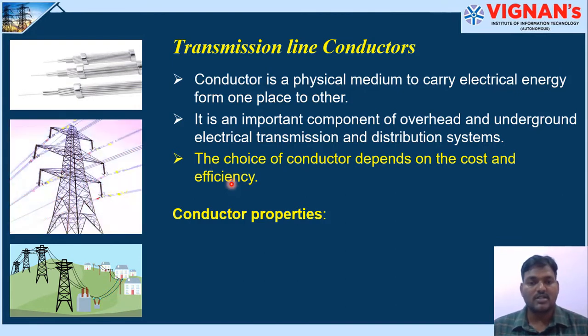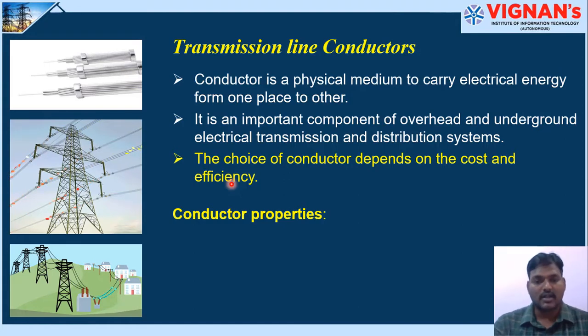Similarly, the resistance depends upon the length and area, or you can say it depends upon the volume of the material. So if you choose properly the material which has minimum volume to give maximum efficiency, you can suitably design an optimized conductor for the transmission system.